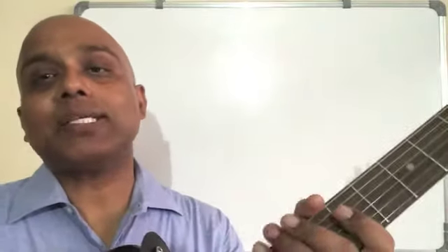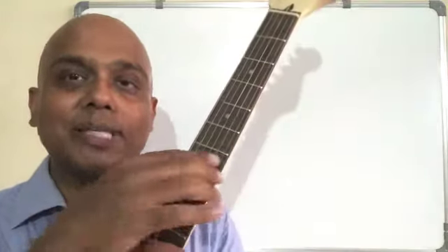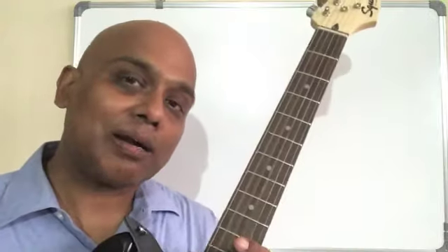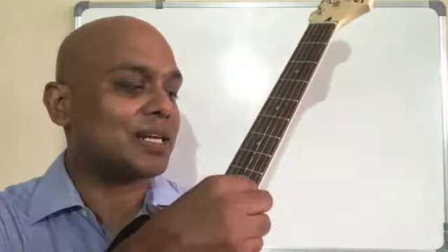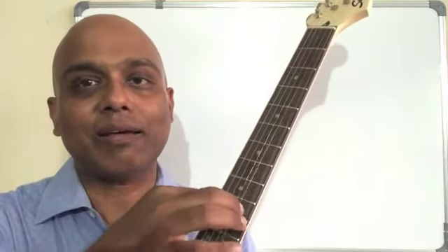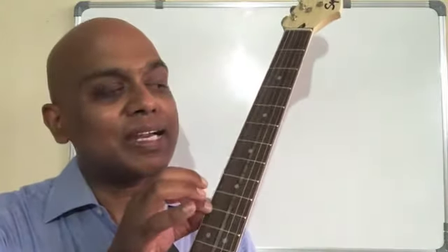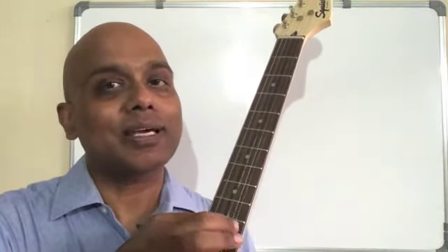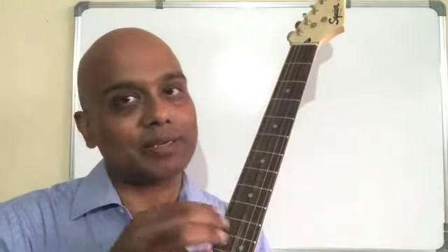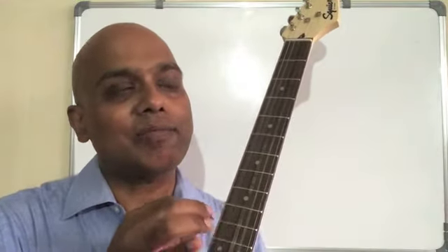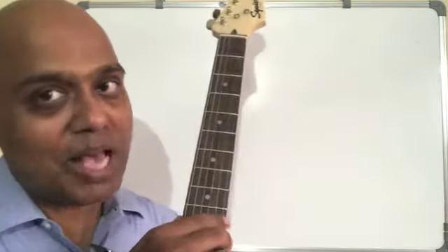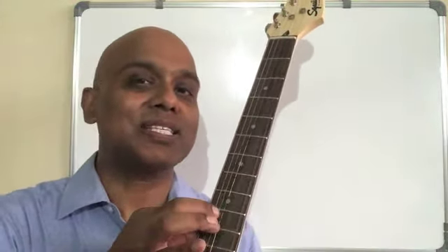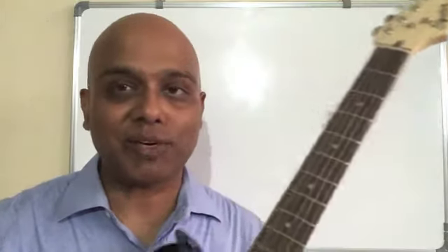So theory of vibration is not complete without the musical instrument. Guitar, basically, has strings under tension, and because of different densities, mass per unit length, they will have different behavior. Even if the tension is the same, because of the mass density, or the mass per unit length of this string, this will have different vibrations here.